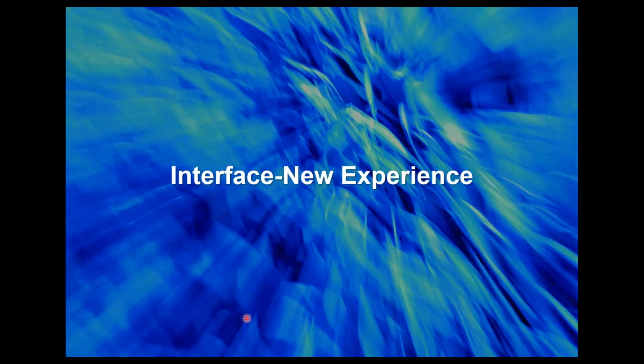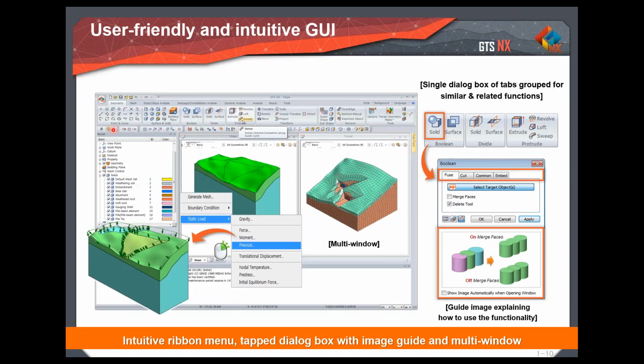This is how the interface looks. You can find at the very top there is a geometry tab. All types of geometric commands will be here. All types of AutoCAD commands have been incorporated. Basically we start with the geometry, and then we go for meshing. In the meshing we go for material and property definition as well, and then we have different types of commands illustrated in different